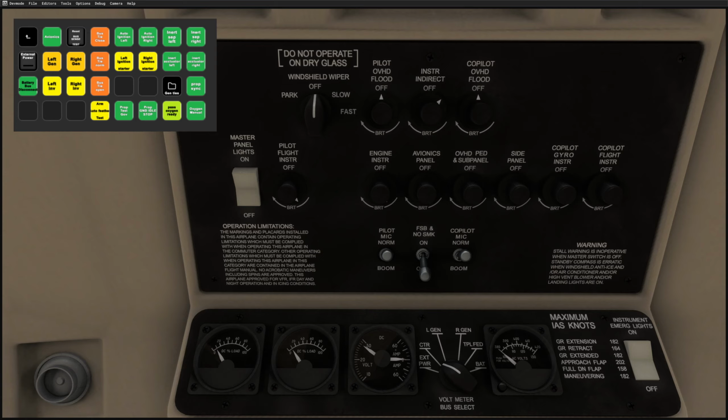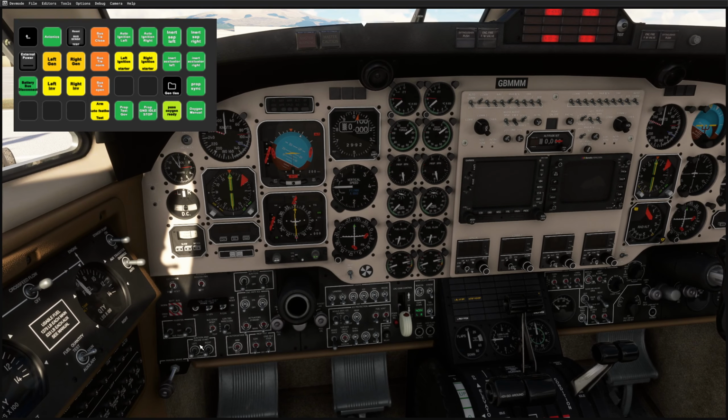And now the next bit that I need to check is the bus sense test. So I need to put the bus sense into test mode. Which is here. So I'm holding that down, and that should be in test mode now. So when I press the test mode, my gen tie annunciator should light up, and it has. Now I'm going to do the reset for that. They're extinguished. So that should be fine.